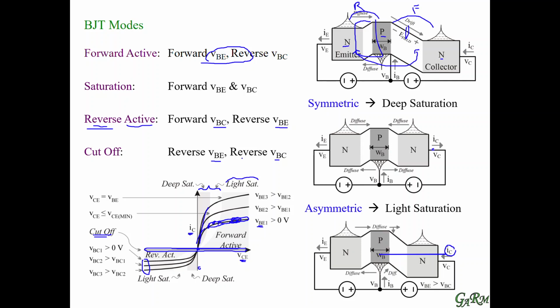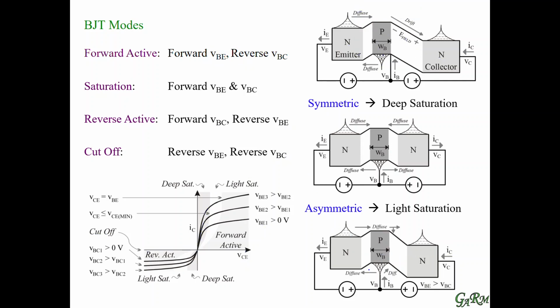One thing to note, however, and I'll remove markers here so I can highlight my meaning. When we design and build this BJT, we make the emitter junction very highly doped. That way we can provide a lot of charge carriers to the base that can go all the way across the device. So the device, although it is an NPN structure that is reversible, is not exactly symmetric.